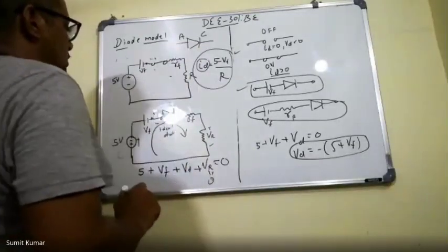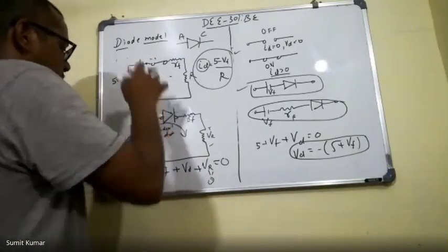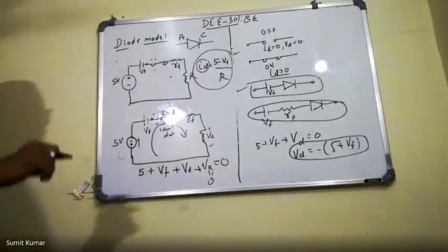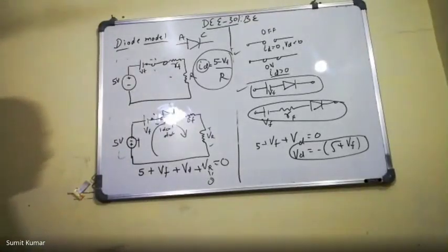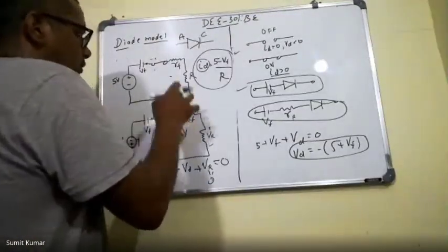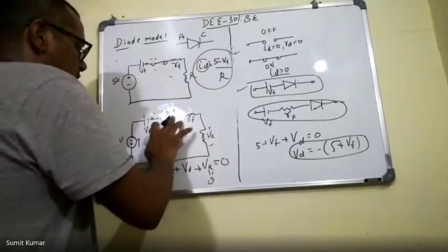And if the diode will conduct, we will replace the diode with the short circuit because it is an ideal diode. Okay, and here again this battery will try to lower the potential at the P side. So it will increase the barrier. So the diode will again be off. The diode will be in blocking mode. So the diode will block.